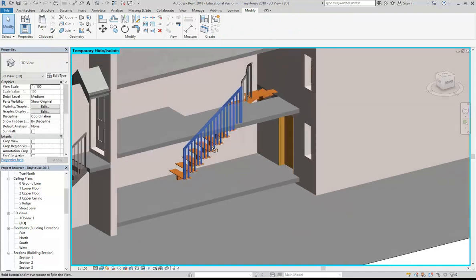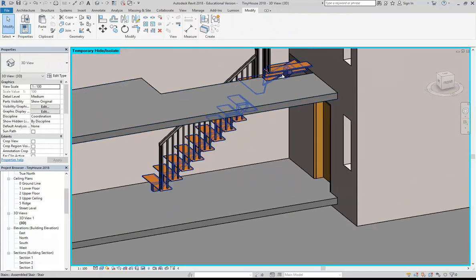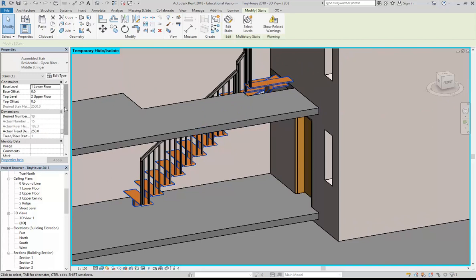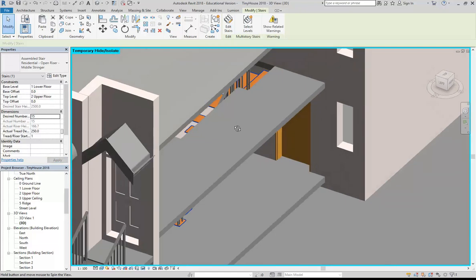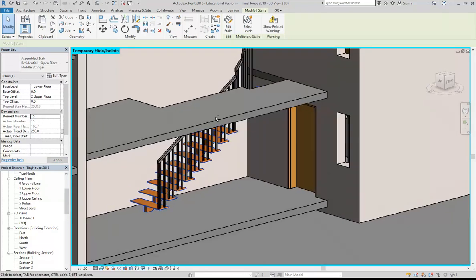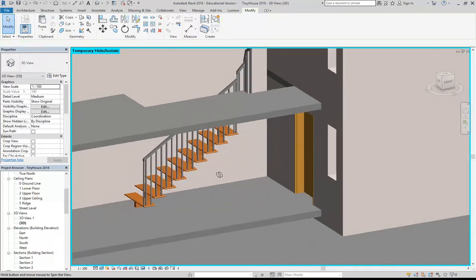And there we are. Now, when I select this, it's gone back to 13 risers because that's the minimum I would need with this stair. It's even better than the last one, but I still want 15, so I'm just going to increase that back to 15 so it's got the right count for what I've done. So there we are. So that's a much better stair.